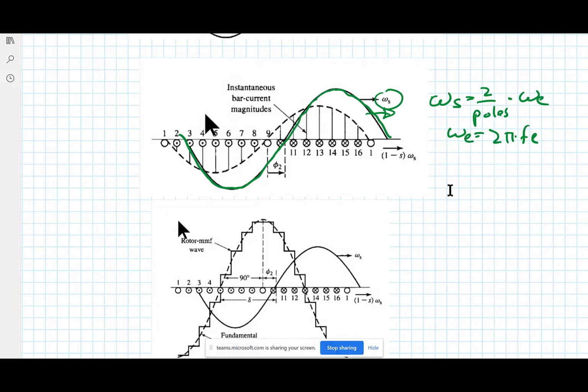And remember, in the synchronous machine, the rotor frequency or the rotor speed is equal to the synchronous speed. So then you've got these induced MMF into the rotor, and you end up with another MMF. We can think of it like we were thinking of the armature before, that's moving with it. There's a difference of an angle here, and this is a very interesting thing.